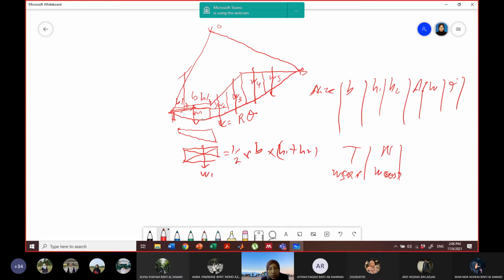So all the slices from W1, W2 to W5 need to be calculated with the trapezoidal formula. And the next one is how to determine the W. I think the W is easy to find by calculating the unit weight of the soil times the area for each slice.